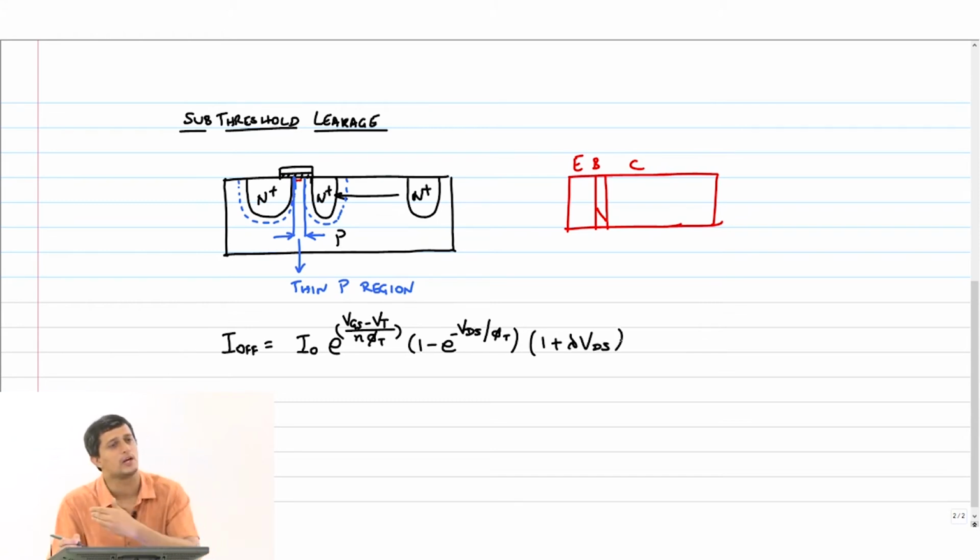This is added basically to get continuity across all the regimes, that's all, right. This will not alter the actual value, okay. So the important part is that my VGS is now going to affect your leakage current exponentially, and so will your threshold voltage.